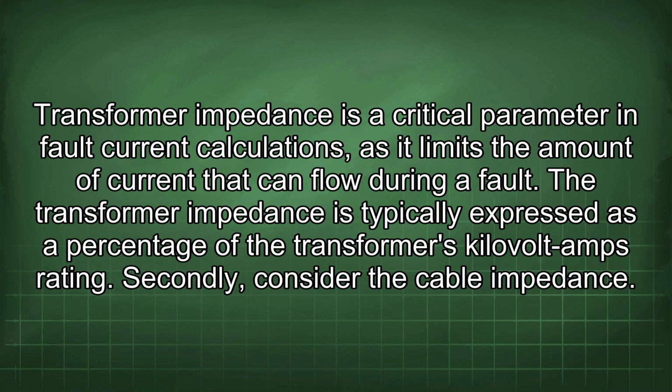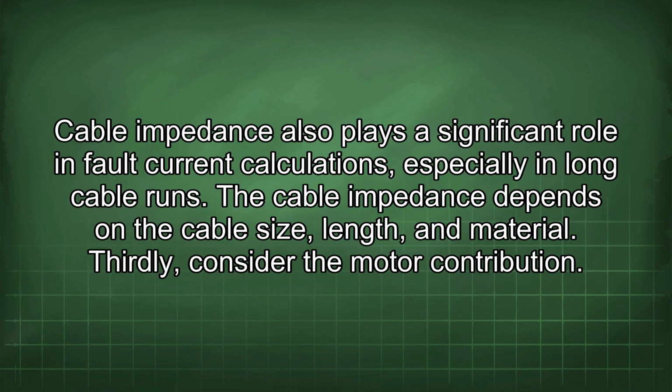Secondly, consider the cable impedance. Cable impedance also plays a significant role in fault current calculations, especially in long cable runs. The cable impedance depends on the cable size, length, and material.